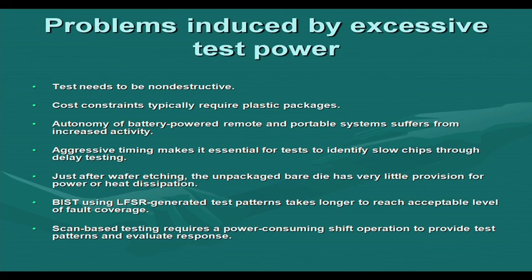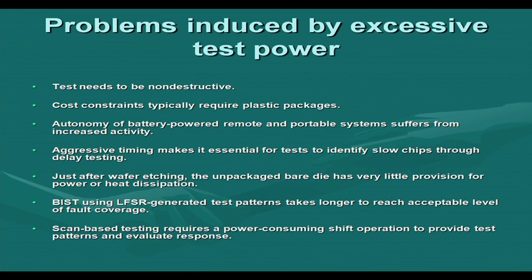Then just after wafer etching, the unpackaged bare die has very little provision for power or heat dissipation. This is the situation where the wafer has just been etched, so the packaging has not yet been done. The connections are not very stable, and as a result they do not have provision for power or heat dissipation. The individual bare die do not have this type of capability. So, we have to be careful, and the test power consumption at wafer level testing should be very low.